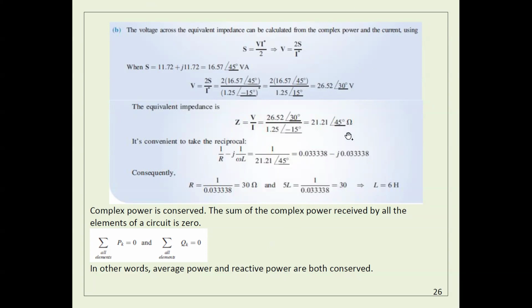So if I take 1 over this part, it's going to give the impedance, which is J omega L. Because I have omega L, now I can get L because I know omega. So X is equal to omega L. Omega is given to me, now you can get L. Any question?